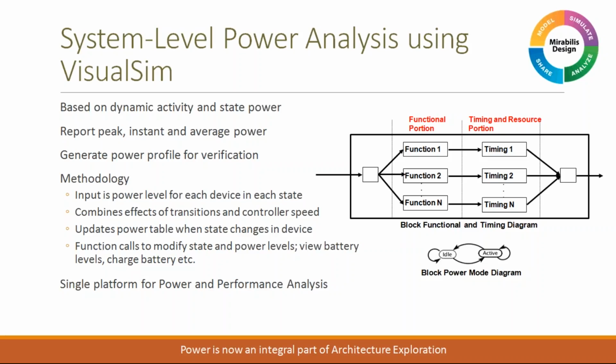So in essence, you're reusing the simulation models that you have used for architecture exploration and performance analysis to conduct power analysis. Or it could be the other way around as well. You can use a single platform and within a single simulation run, you can monitor both power as well as performance analysis.